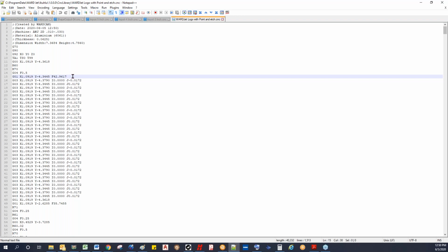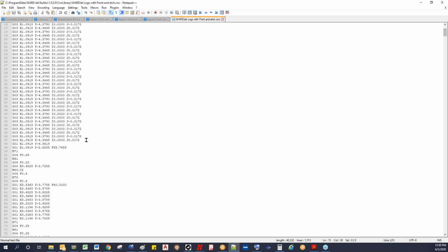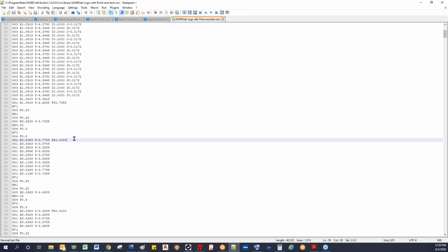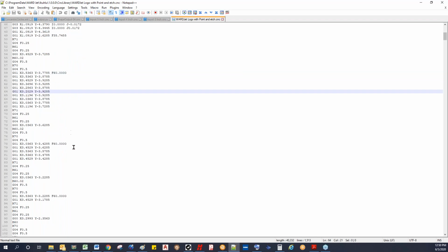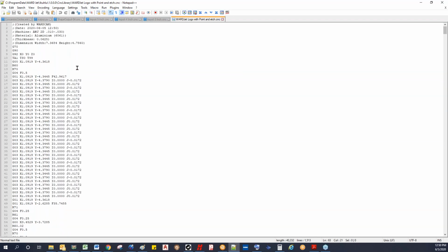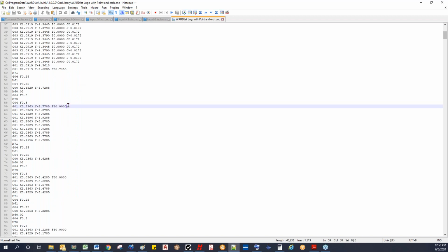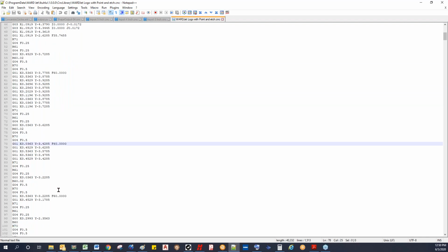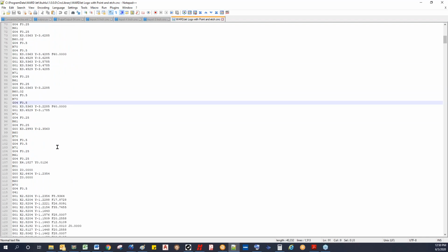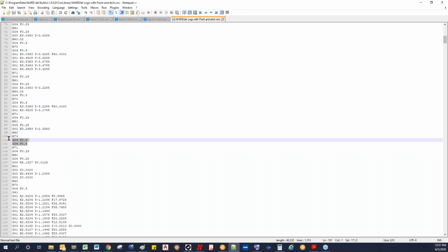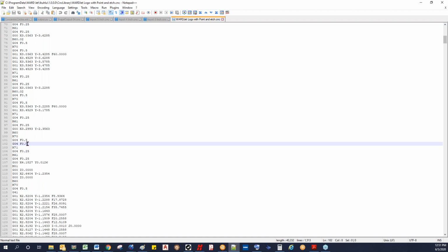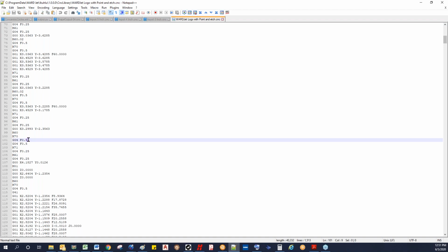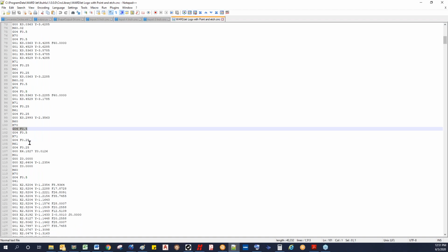So basically what we've got here at the start is the etch. Actually, I'm sorry, the first one was a slit cut, and then we've got our etching, which we had told it to do with abrasive, so that's why it's got the M70 there. So it does those. And then it's gonna go over and do that abrasive pierce at this location here. So we've got a 1/2 second delay where the water and the abrasive turn off, as well as a 1/2 second delay that we told it we want as a pierce delay.